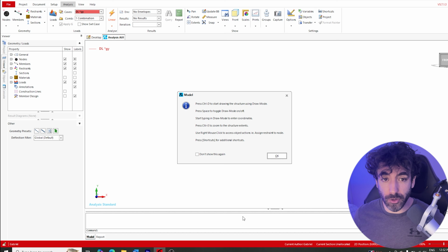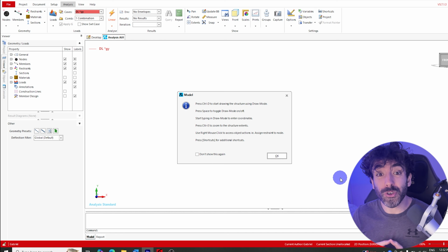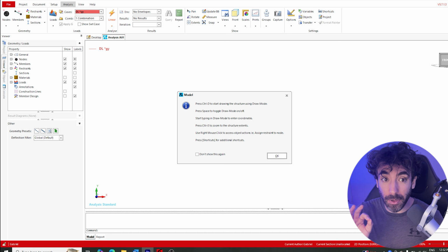Know what your model needs to achieve before you even start modeling. Are you analyzing both vertical and lateral forces? Do you have to model bracings, shear walls, or can you just apply a support and design these elements separately in a spreadsheet or by hand? If you're starting out, I wouldn't overcomplicate things. The simpler your model is, the better.